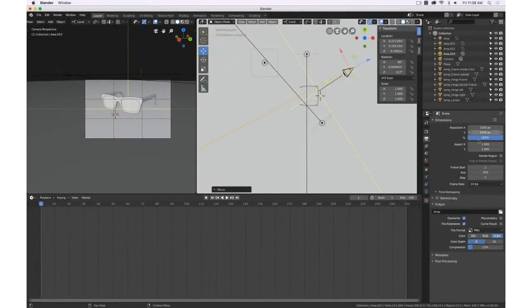For just the image, we can render out 25%. We can render out 100. We can also make this double as big. So something like this is close to 8.5 by 11. And with 200, that would be an 8.5 by 11 rendering, so letter page or DIN A4 with 300 dpi. This would be 100 dpi. If you need to make a rendering for a particular size, go to Photoshop, make an image to the size, and then take a look at the resolution and enter it in here. That's one of the easiest ways to do it.